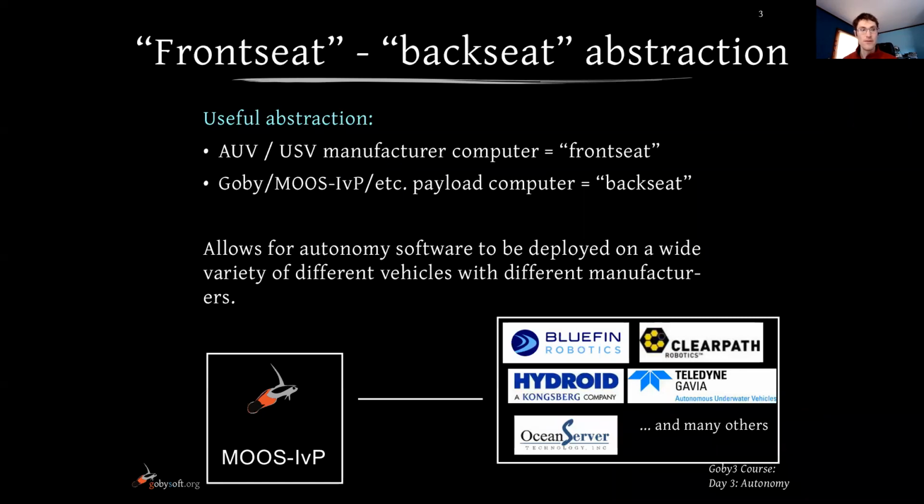Basically you have a front seat driver, the vehicle computer, like the manufacturer's computer, which is generally tuned for a specific platform's control paradigm and design. And then the payload computer, which is referred to as the backseat driver because it's telling the front seat what to do. So that's MOOS-IvP, Goby, etc.